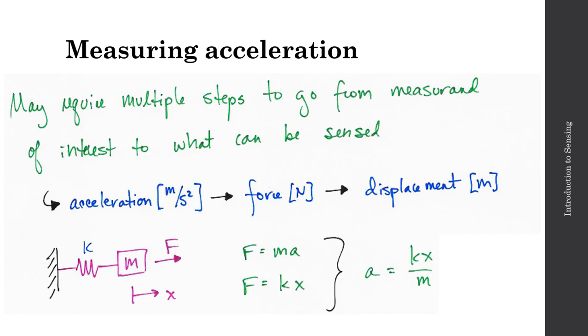So an example of a measurement for x, this might be some sort of capacitance output, right? The capacitance is changing with respect to the acceleration on the mass. So I'll need to design some interface electronics then to convert that capacitance to a voltage that can then be digitized by an ADC on a microcontroller.